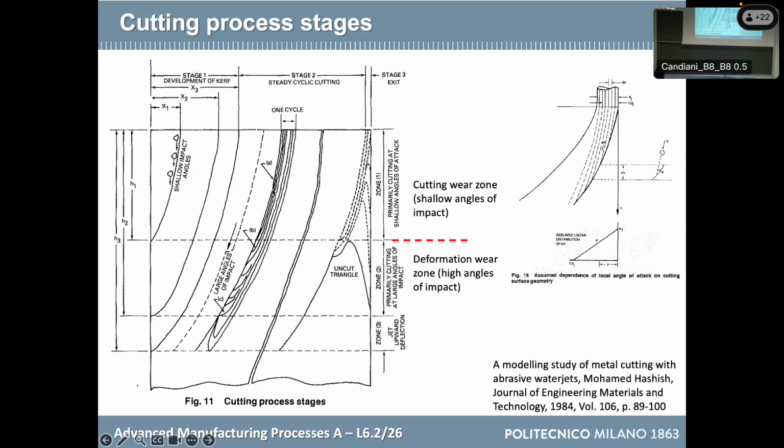So here, the jet is really effective in creating an almost vertical cutting curve. And in fact, if I look at the side or at the wall of a cutting curve cut by water jet, I can clearly see that at the top, I cannot see any striations. It is homogeneous. It is really similar to an EDM cutting curve, even if here the principle is completely different, and in any case I have particles that are creating some striations. But if you look at it, you cannot distinguish any striation here.